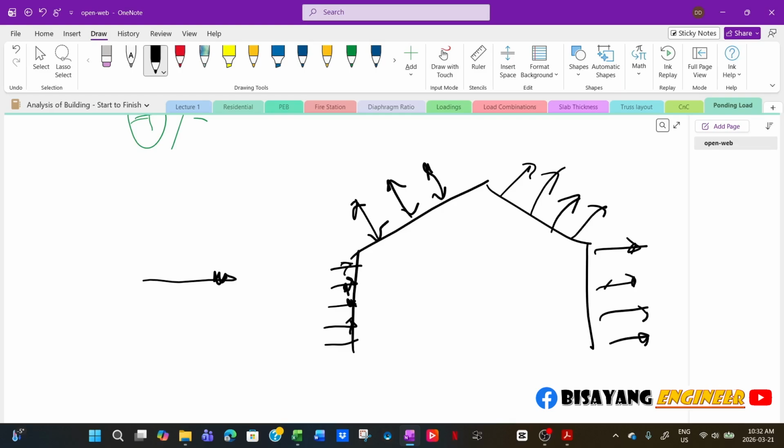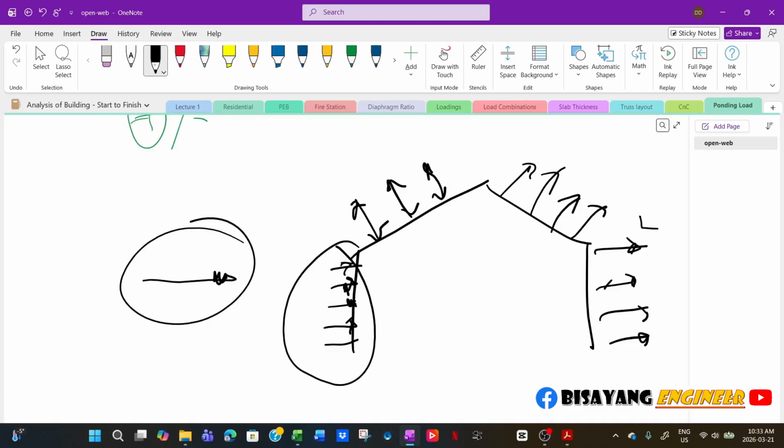In his post, he said load case one is windward only. You cannot say that. When you apply the wind load, it's always together, leeward and windward. These are just directions, or which side of the building you are on with respect to the direction of the wind.